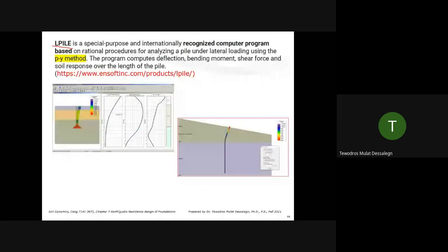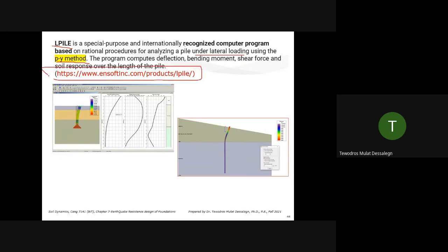This LPile, the software I mentioned before, is a special purpose and internationally recognized computer program based on a rational procedure for analyzing piles under lateral loading using the PY method. The program computes deflection, bending moment, shear force, and soil response over the length of the pile. You can read more about this software. When I was a student like you, we had a student version of the software in school, so we played with it a little bit. It's not that complicated. It's very easy software. It has a user manual and is very easy to understand. But that's what it does.